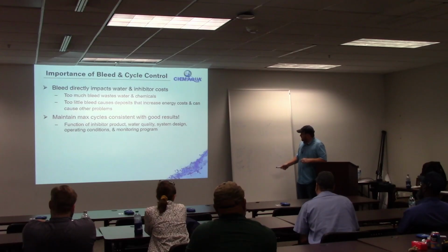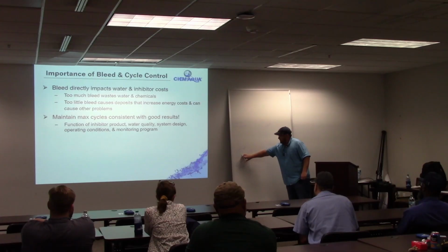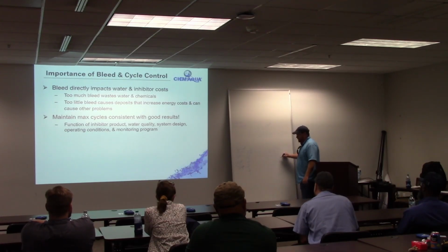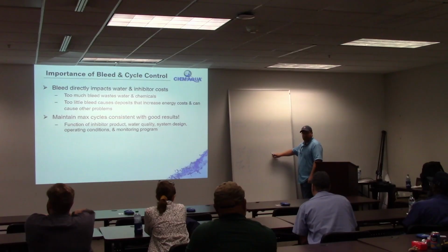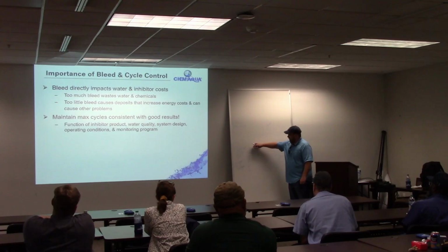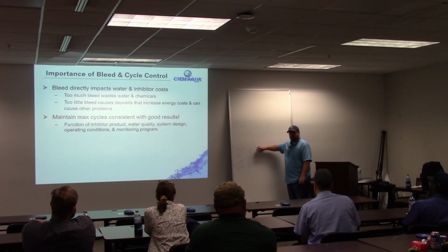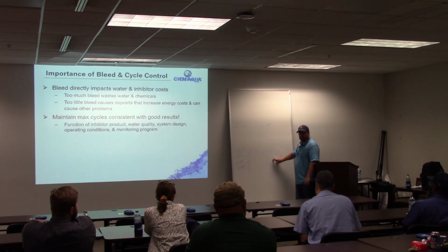Also, just so y'all understand, if this is our set point and we get to this point, that's when the water treatment controller is going to initiate blowdown. We're going to blow down some of that concentrated water that's got 30 marbles dissolved in it, right? And we're going to bring in makeup water that's only got 10. Does that make sense? So we're blowing down something that's more concentrated and bringing in something less concentrated so that we maintain that level of mineral saturation in the water.